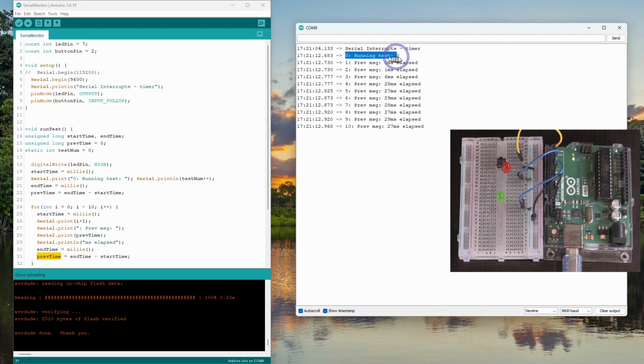Actually, that was the message. It will definitely fit into the buffer, so it's basically copying that into memory, which is very fast. And then it relies on the USART to send that out. And that's our report. So it says 0 to print this one. Now this 1 millisecond is for this one. The second one says that message number 1 took 0 milliseconds.